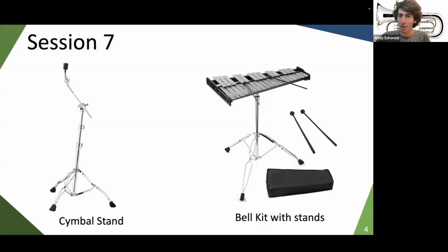And then afterwards, we're going to do engineering drawings, because part of what we'll do today is create an instruction set to tell you how you're supposed to bring everything together. In order to create an engineering drawing that will include potential dimensions and a couple of notes in terms of how you're supposed to build that, we're going to create something known as an exploded view, where you take this, currently assembled in its final form, and it's all exploded with different parts appearing in different areas.